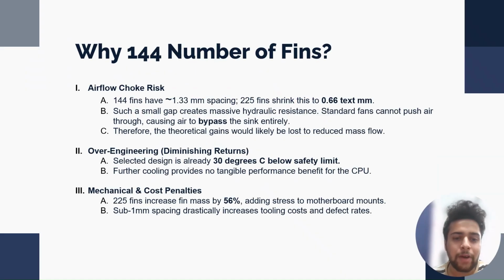Let us now see why we have chosen 144 number of fins. First reason is airflow choke. Whenever the number of fins increases, the spacing between each fin decreases, and this can make the air totally bypass the heatsink, as standard fans cannot push the air in.